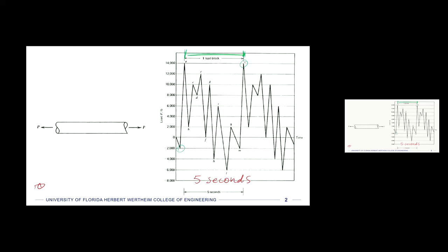If the material is 4340 steel, heat treated to a specific hardness, which is not relevant to the problem, it just says that we can use the data from figure 8.14. And the true fracture ductility has been determined to be 0.48, which is one of the coefficients in the equation I just talked about. What size should the cross-sectional area be made to support the load for a design life of 15 minutes, if a safety factor of 1.2 is desired?